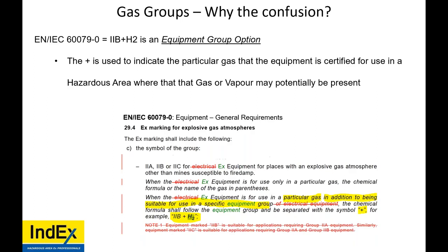Now, where I say sequential order, in training programs that we have put on under different schemes, IECEx, Competency, others, there is confusion in the industry in many countries when it comes to gas groups and temperature classes, because T1 is the hottest, the most dangerous piece of equipment and most strict restriction for an area that there is. So you would figure 1 would go with A, 2, B.